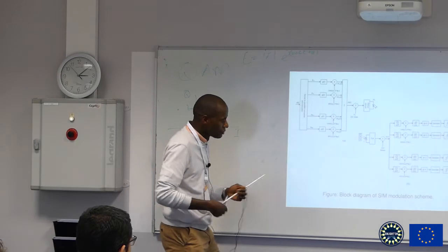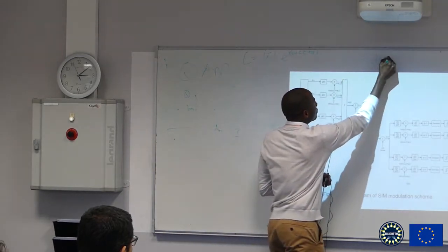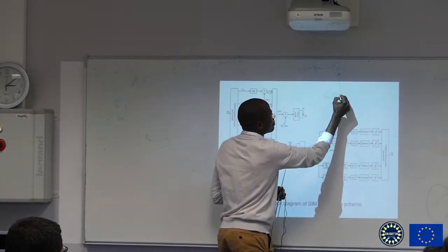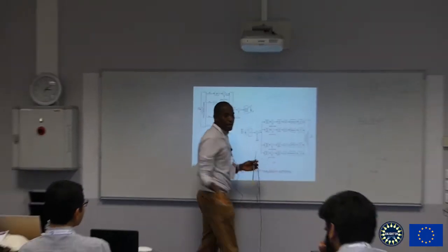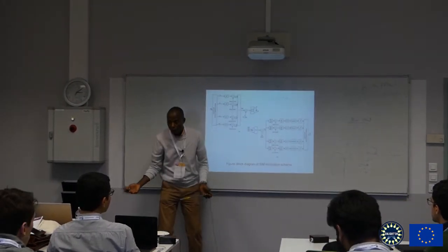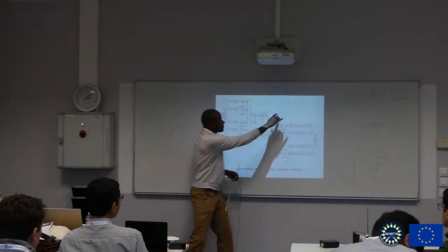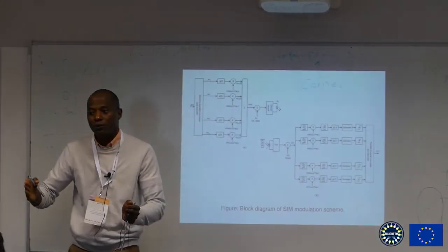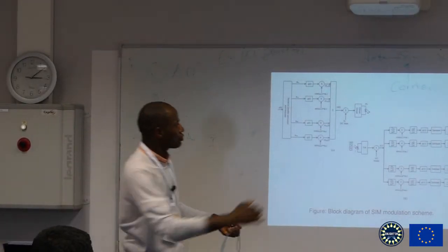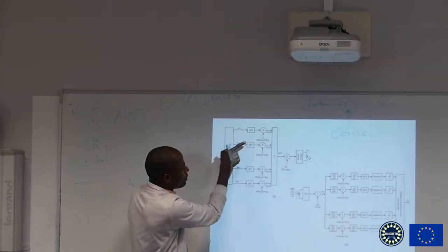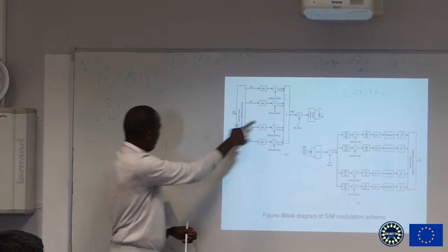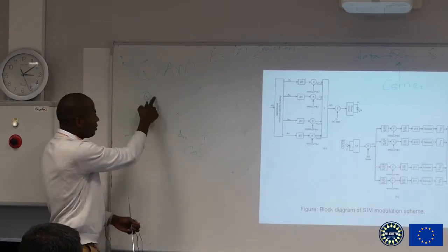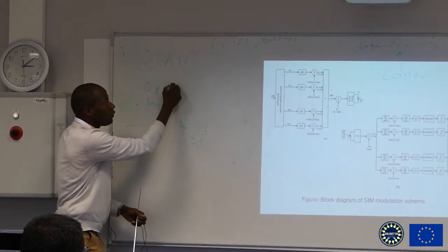Essentially, what we are doing here is you got your data, you modulate it with a carrier, and you get the modulated signal out. That's what we do in RF as well. That's the basic of modulation, except that this carrier has to be very close to baseband. It has to be in the passband of your system. So we do just one, we modulate it. By the time I do multiple, I do for cosine and I do for sine, because the real one here is the one for the cosine, as we know, and the Q one here is the one for sine.